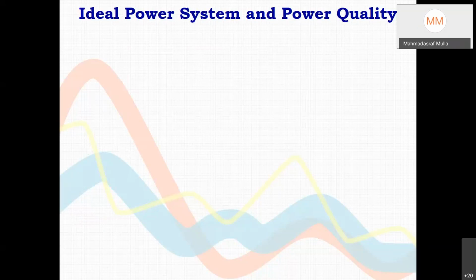That mismatch is not because of phase angle now, but because of the non-sine nature of current, which has the same effect as the phase displacement between voltage and current. So we are drawing more RMS current from the conductor and utilizing more volt ampere capacity of the transformer. A transformer designed for 50 Hz is having other frequency currents drawn from it. So many issues these circuits are creating.